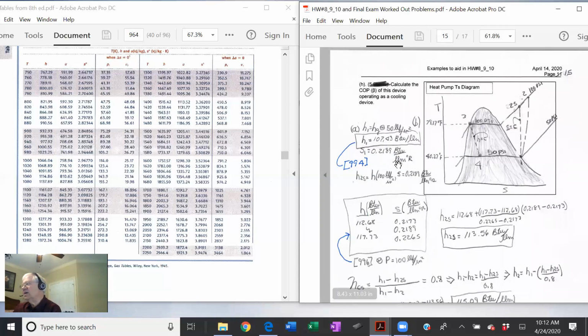Now, here's a TS diagram. It's not complicated. This is refrigerant R134A, which operates under the dome and outside the dome: 2 phases, liquid, vapor, and a mixture. So there is indeed a dome involved, just like with steam. And we have 2 pressure levels here. High pressure, as seen, was 100 psi. There's a high pressure, 100 pounds per square inch. Low pressure is 50.